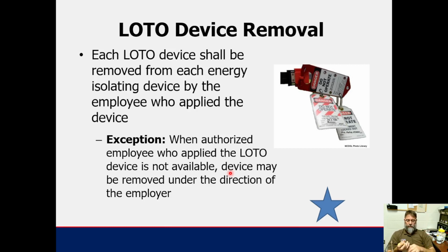And both of us are working on the machines, but if he needed to unlock it for whatever reason, and I'm not here, he would probably call me to say, hey, is that machine safe to be unlocked? For all he knows, I could have something removed from that machine, and if he just goes over and unlocks the machine, then injury may occur. So just because we're the only two here and we know what each individual is doing, we're not going to remove that lockout unless we have received authorization from the other individual.